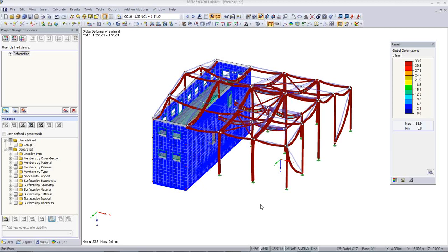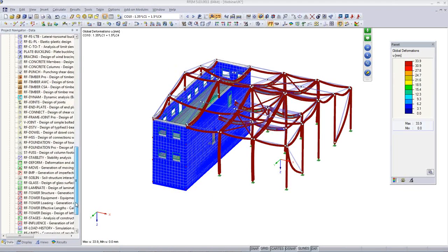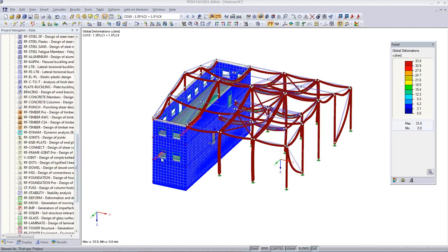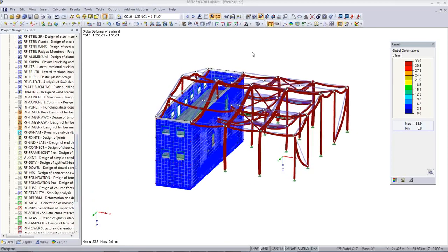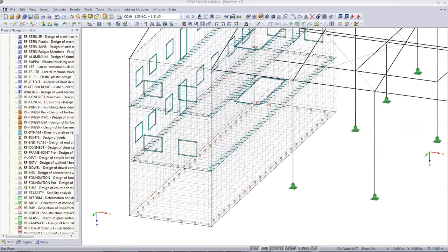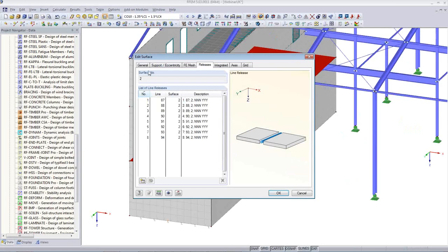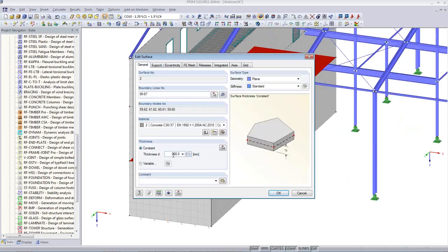And one more thing I forgot to do before we update the final results inside Revit and the other software. I changed the cross section or the thickness of the slabs here, and I want to do this in my main model again, so we get the right changes back to the other software packages.